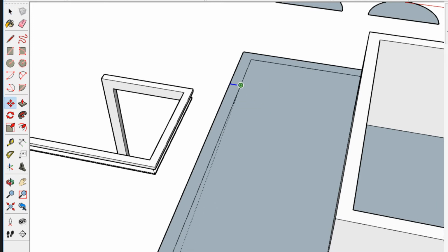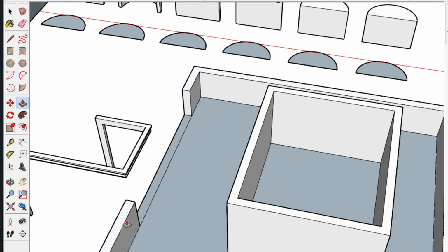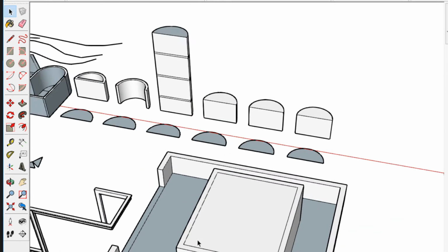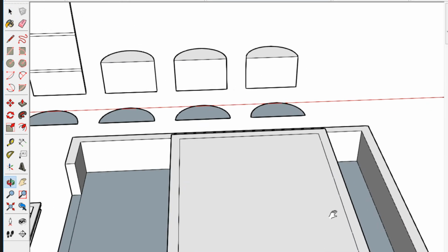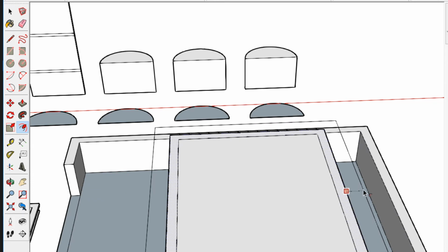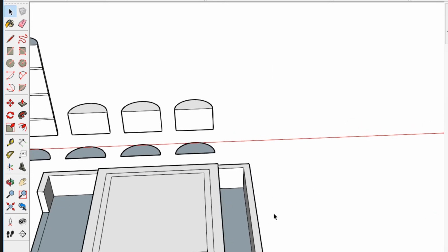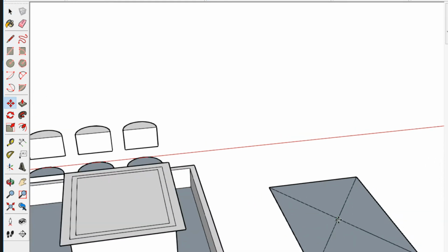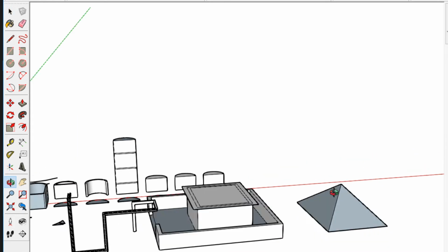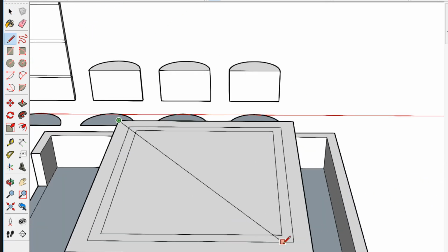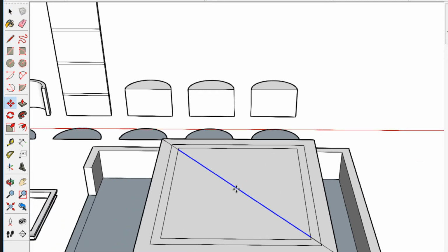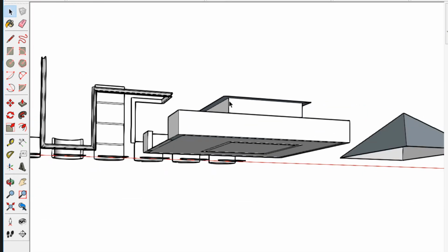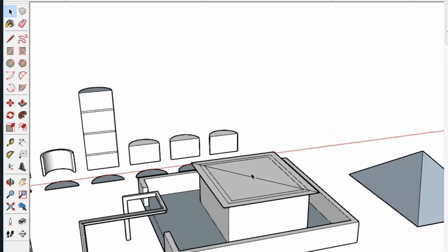You can also copy that instead of drawing it over again. Let's say the walls are that big, and then let's say I have a weird roof. If I offset outside, it's okay. But we are used to the roof where we put something like an X and then pull the middle using the up arrow tool. In this case, if I put a line all over and try to pull this, these stretch because they're not separated. They're like glued together. A way to unglue them is to put them in groups, but we're not yet there.